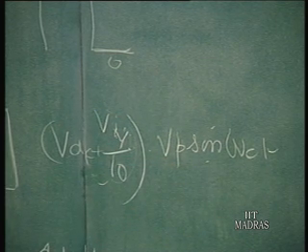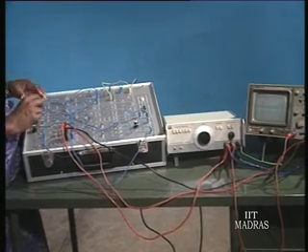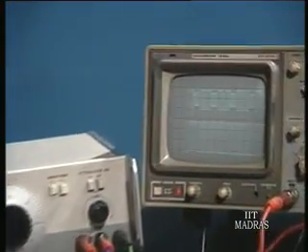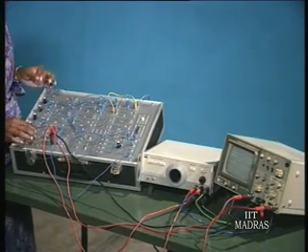Now, that is demonstrated to you by Devaki again, clearly bringing in a DC, and an AM. Now, let us concentrate on the screen. The output of the multiplier corresponds to the amplitude modulated output. You can see the amplitude modulated output here. Please go to another lower frequency range, please. You can concentrate on the screen meanwhile. So, you can see the amplitude modulation here. It is going from the maximum to minimum abruptly, because it is a square wave.